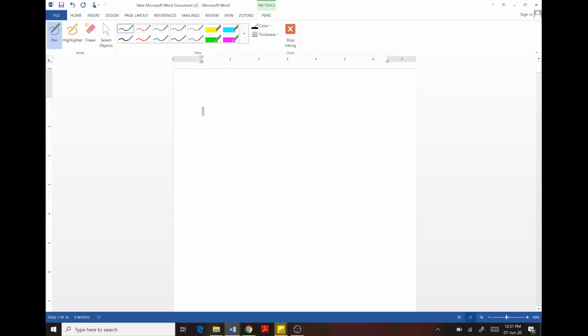So today we will solve a problem of cantilever sheet pile in cohesive soil. In the previous lecture we have solved a problem which was in cohesionless soil. Today we will solve a cantilever sheet pile problem in cohesive soil. Cohesive soil, that means phi equals to 0 and there will be apparent cohesion in the soil.